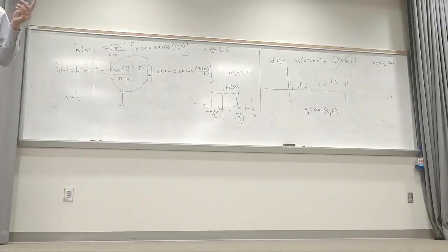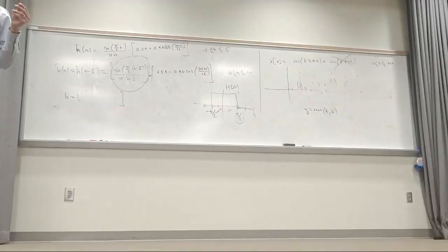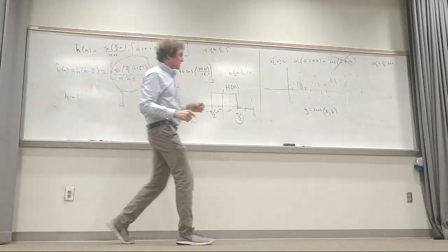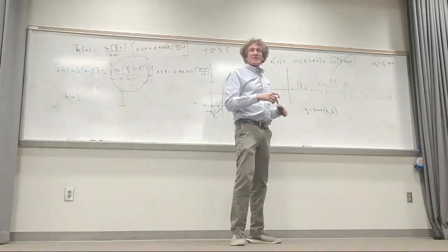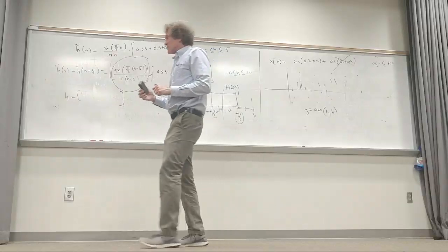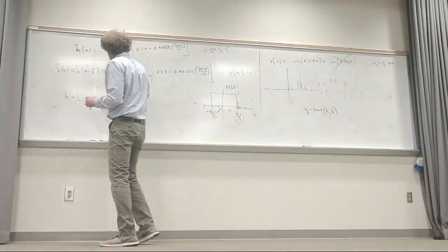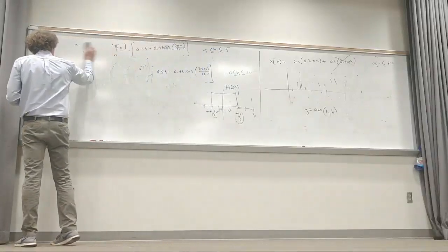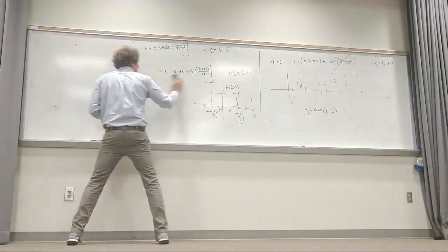Now, the first filters, just RC and LR filters, have a maximum reduction rate of 20 dB per decade. If you had an L and a C, in a low-pass filter, this has got a reduction of like 50 or 60 dB per decade, which is phenomenal. And it's a very easy filter to build. I believe it's that much, but I didn't actually check.